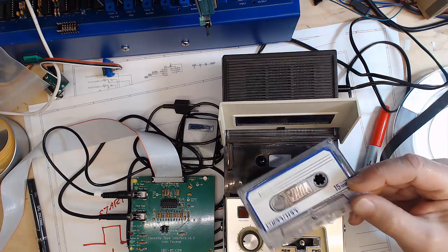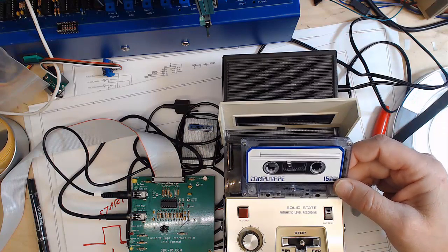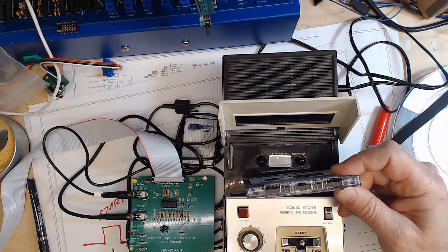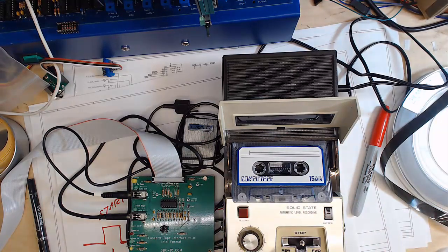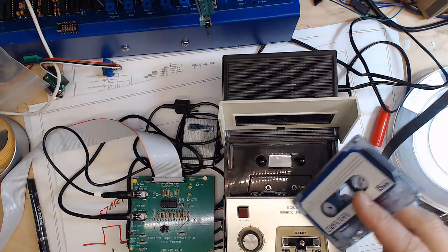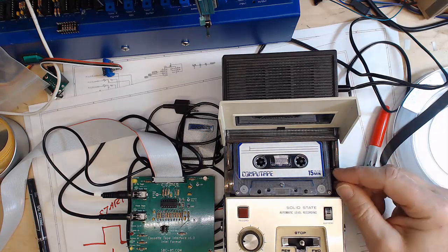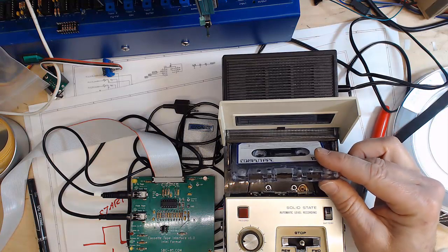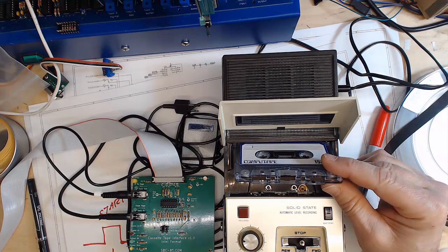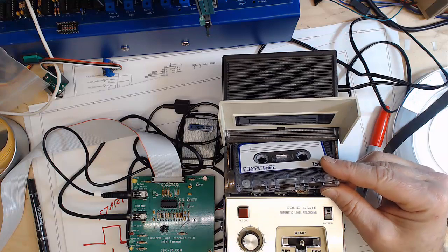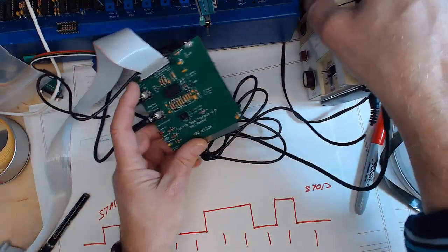So you can't store just data on this in serial. If you just had a serial port and you tried to just store stuff on this as ones and zeros, it wouldn't work. This is only 2 tracks of data. There's 1 track when you have the tape in this way, and 1 track when you have the tape flipped over in the other way. Newer cassette players came out and they were 4 tracks, so you had stereo on each side, so you had 4 on this side, or 2 on this side and 2 on the other side, of course. But nonetheless, with the speed that this is going, a couple of inches a second, and the width of that tape, it's just not possible to store the data in parallel format, and even storing it serially has got some major problems. So let's look at a serial data stream and see what problem crops up.